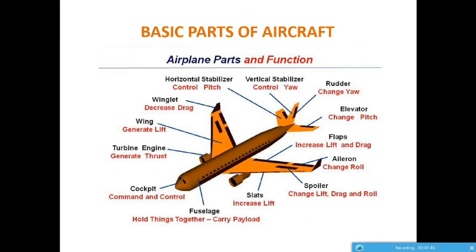Usually the motion effect caused by the rudder is also dependent on CG. That is, if you give a small roll using these ailerons, then according to the position of the CG on the aircraft, either forward or to the backward, the aircraft tends to yaw in the particular direction of roll. But in most aerobatic aircraft, the CG is very neutrally stabilized, so that each control surface serves only one purpose and not multiple.